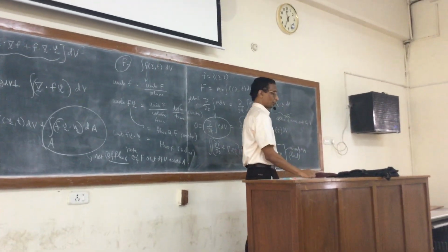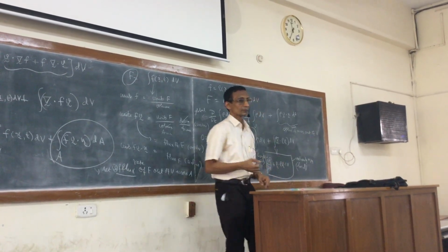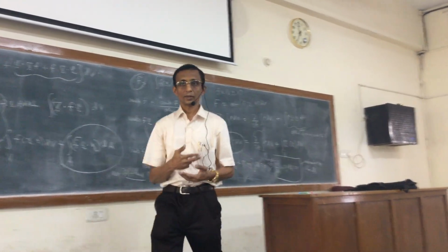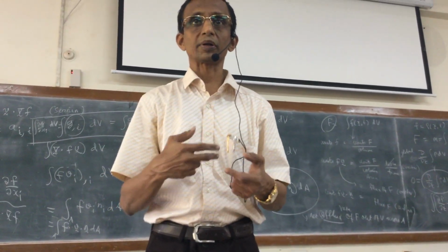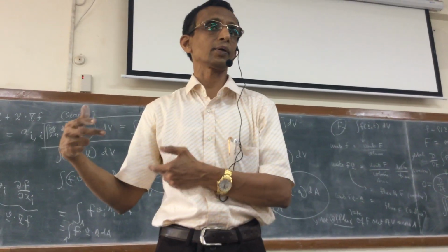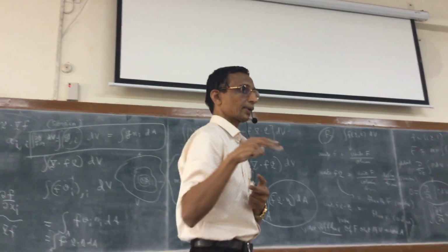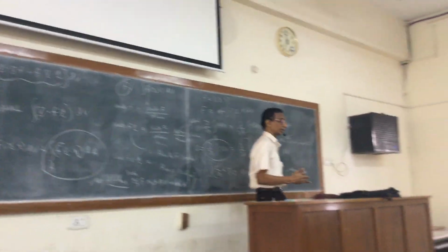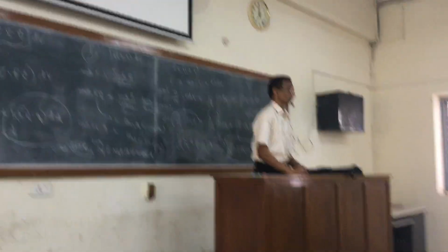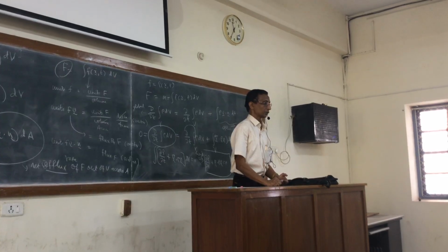In the limit I can prove that, as I shrink the volume around the point which I am going to consider as a body of interest and proving that the integral is zero at all stages, in the final limiting case I will argue that the integrand itself has to then be zero. This is what is called a continuity equation.